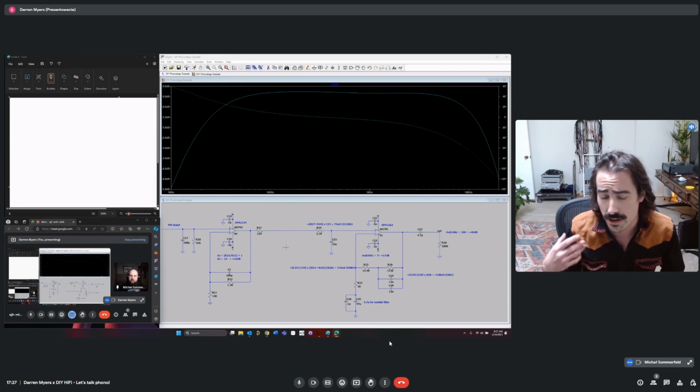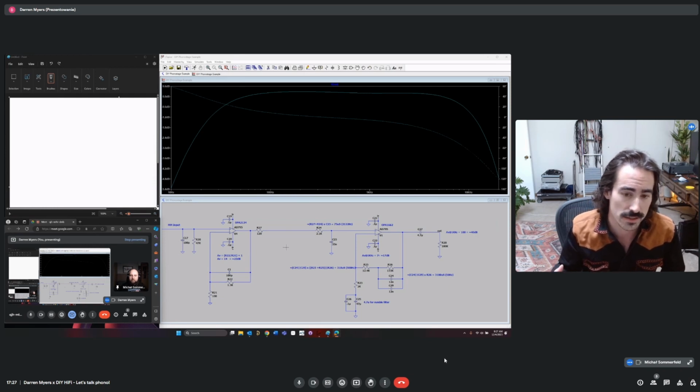So they're really not able to, because these higher order compensations need larger capacitor values. They can't do that on the die, and they also don't want to burden the designer with having to stabilize it themselves.